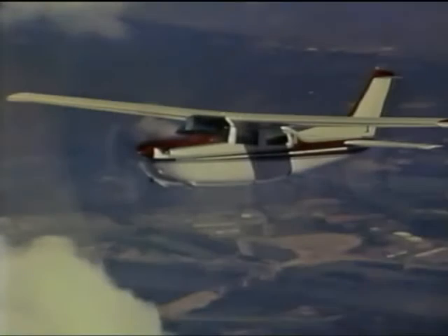A constant speed propeller system is one in which the propeller blade angle is varied by the action of a governor to maintain a constant system RPM. The action of the governor allows the RPM to be held constant with changes in engine power settings and aircraft speed. Constant speed systems are used on most modern, medium, and high-performance single-engine aircraft.